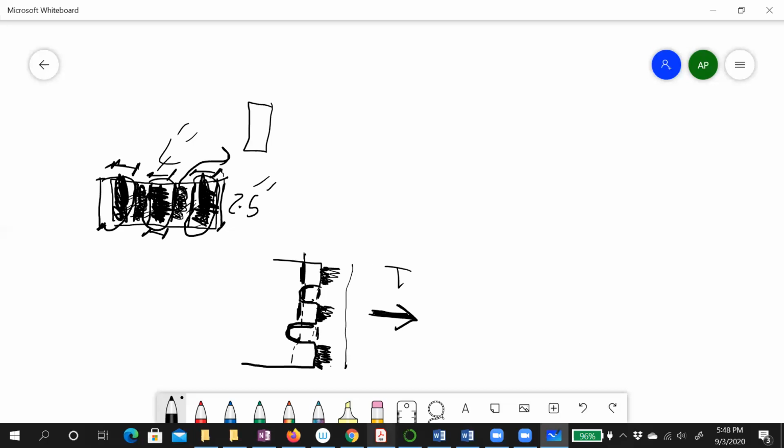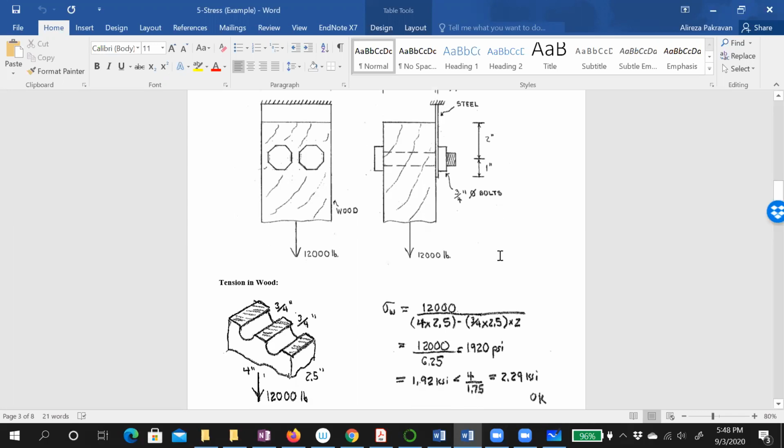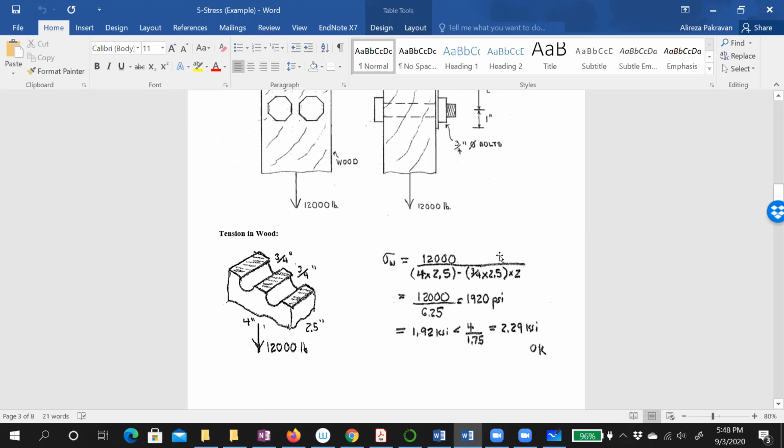So let me go back to here. We pick the middle of the bolt, which means we remove lots of area to find the minimum area, because we want to find the maximum stress, to see the maximum stress in comparison to sigma allowable. Then if it works, the other sections also work well. Yeah, that makes a lot of sense now. Thank you.